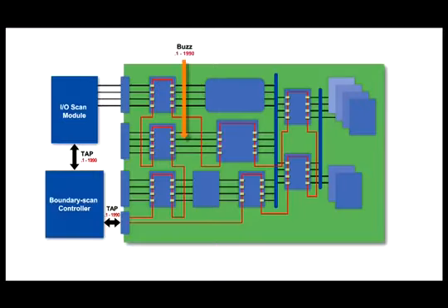The most simple example is a continuity measurement to check the connectivity of a particular connection. This so-called buzz or ring measurement is frequently used in R&D as well as manufacturing repair and field service repair. Traditionally, a multimeter is used to ring out a connection. Using boundary scan, this measurement can easily be performed by selecting the drive pin and sense pin. A connection is present between these pins if a specific stimulus applied at the driver is seen by the sensor.